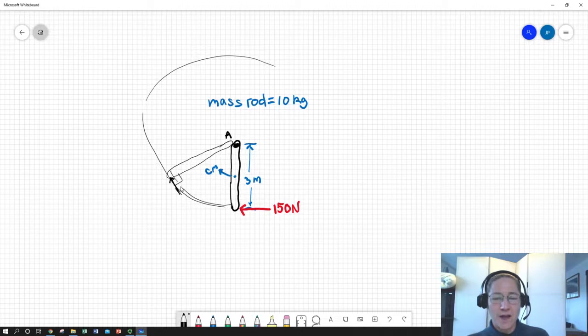Now, as we push the rod up, that force is going to result in an increase in kinetic energy and an increase in gravitational potential energy. So we're doing work against gravity, and we're also contributing to a rotational acceleration. In this case, the center of mass is moving to a new position. So we're going to have expressions that include the rotational kinetic energy, and a change of position of the center of mass. Because we're not rotating about the center of mass itself, the velocity of the center of mass is not equal to zero. So when we look at kinetic energy, we're going to have to look at the kinetic energy of the mass center moving, as well as rotational components, or look at a way to relate them together.